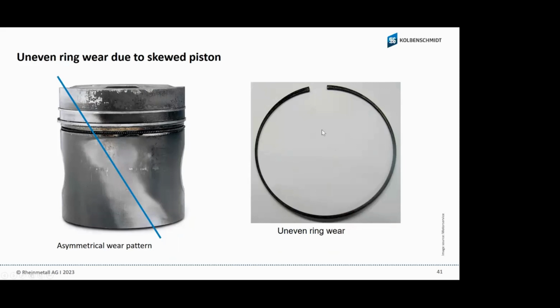On the open end we have no wear, and also at 6 o'clock we have no wear. When the piston rings are not round, they cannot seal. And when they cannot seal, oil jumps up to the combustion side. We have a lot of blow-by, and oil goes into the combustion side and builds up carbon, and then the story starts again.